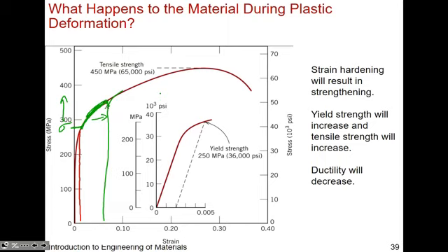But you can definitely do that, and that will increase the strength of a material by decreasing the grain sizes, because that increases the number of grain boundaries, and that will impede dislocation movement, and thus your material will be stronger. That is something that will come up in about 10 slides or so.